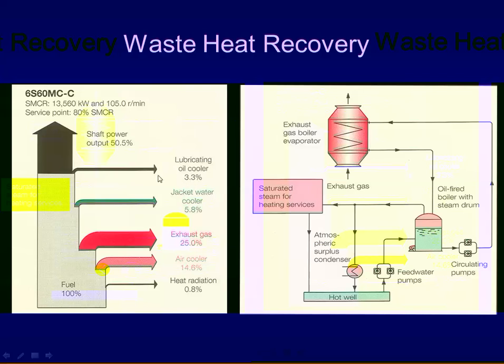Lube oil cooler, it's about 3.3%. Low grade heat, you're only down about 40 C. It's not enough, so you really can't recover this little bit of heat. I've never seen anything where they recover from a lube oil cooler. Jacket water, 5.8%. Yeah, we can do that. We can recover that for our evaporators.